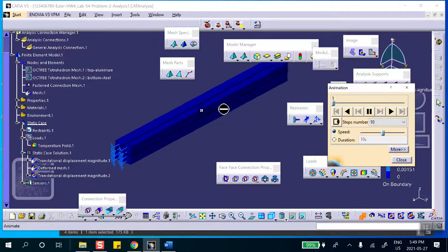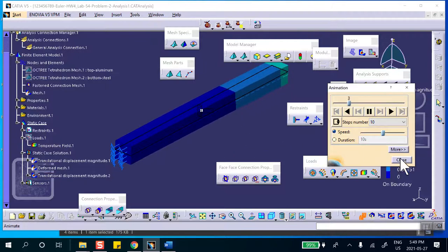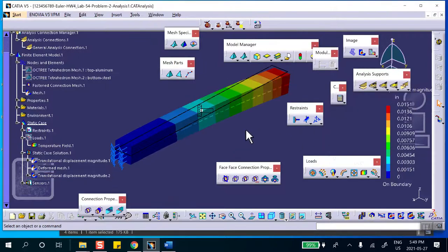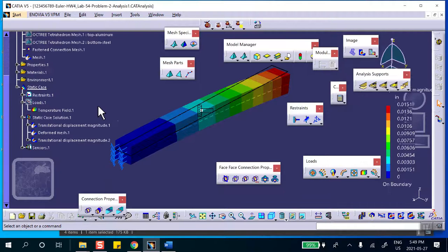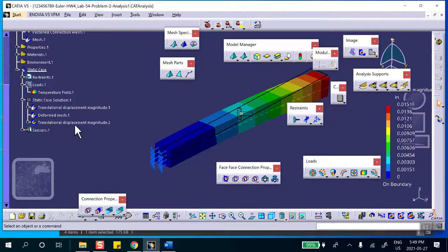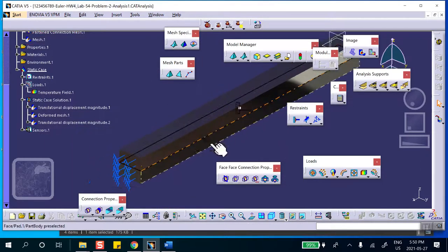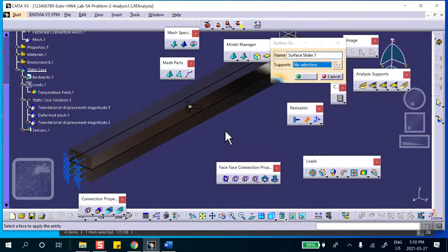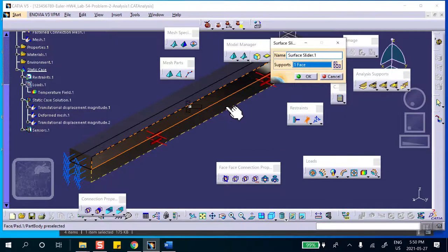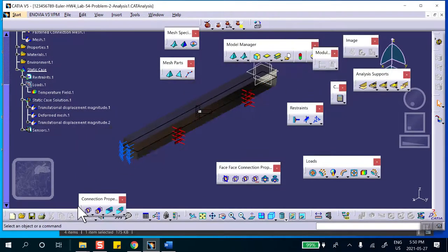Okay, the only difference between this problem and the one that's done in the book, oh, I forgot surface slider. Oh, I lost 5 marks. Okay, so let's deactivate this. See, it happens to all of us. Remember, I made a cut here. It looks the same, but it is not right. Okay, so surface slider here, surface slider there. Good, and save it and run it.